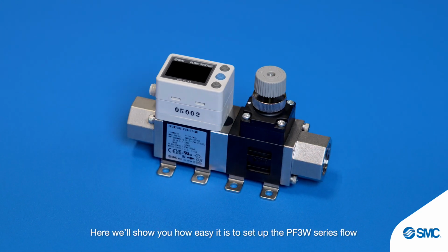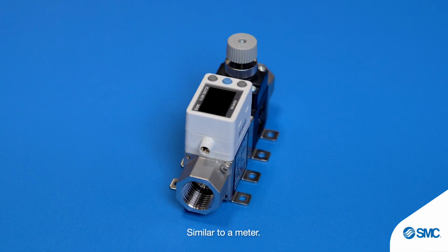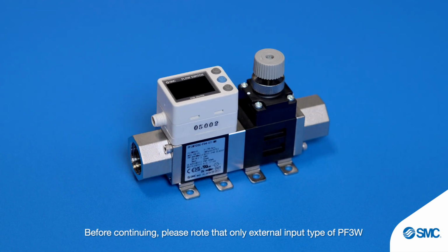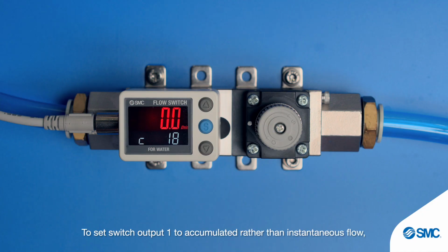Here we'll show you how easy it is to set up the PF3W series flow switch to operate an output once a measured flow volume has accumulated, similar to a meter. Before continuing, please note that only the external input type of PF3W allows reset of the accumulated flow value. Let's start. To set switch output 1 to accumulated rather than instantaneous flow, first press and hold the